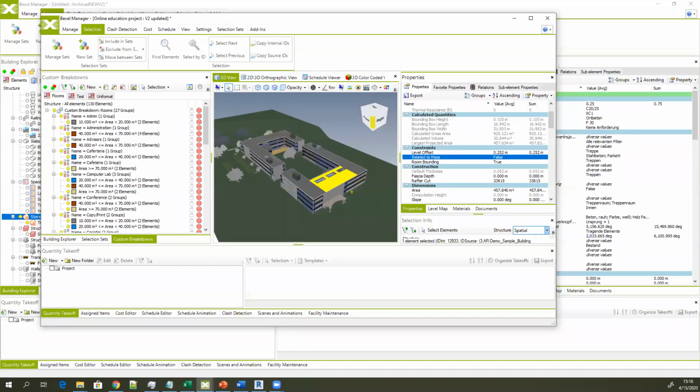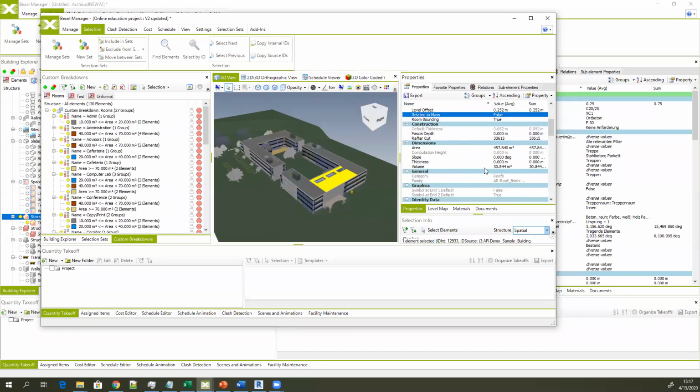Is it possible to reorganize or remap the structure of the properties group? Currently, you can only create your new groups, and the existing structure is coming from the authoring tool or from the IFC files, so it's not currently possible to reorganize it. And this is maybe not really recommended, because sometimes according to BIM execution plans, you specifically want to put a specific property into a specific group.